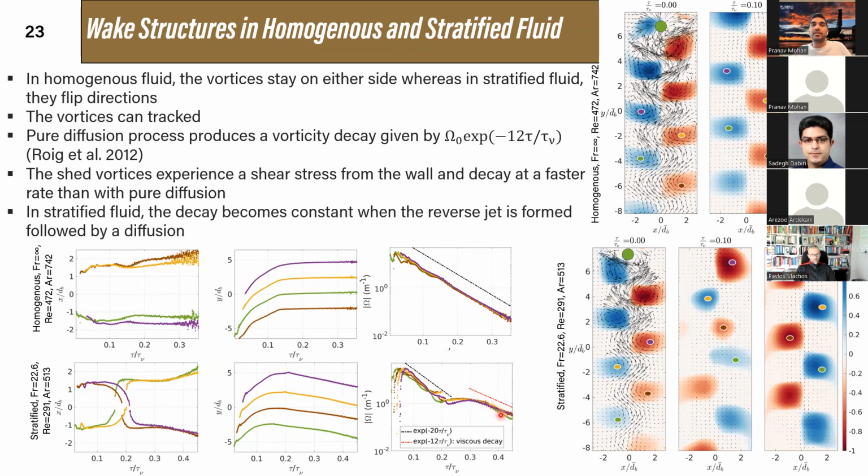The slope that the vortices follow is the diffusion. So what happens in the center region? Well, the vortices naturally, because of diffusion, will decay over time. Now, you can imagine that if the vorticity in a vortex continues to stay the same, that means some kind of additional energy is being added into the system for the vortex to continue the rotation.